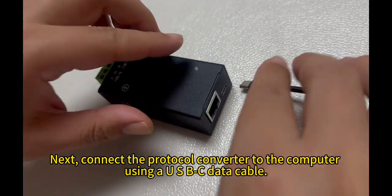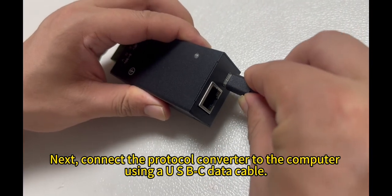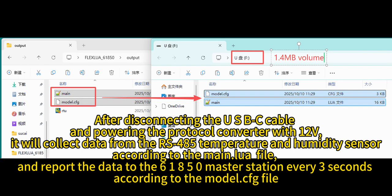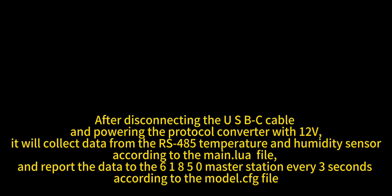Next, connect the protocol converter to the computer using a USB-C data cable. Then drag the newly generated main.lua and model.cfg files into the protocol converter's 1.4 MB USB drive to complete the entire configuration process. After disconnecting the USB-C cable and powering the protocol converter with 12 volts, it will collect data from the RS485 temperature and humidity sensor according to the main.lua file, and report the data to the 61850 master station every 3 seconds, according to the model.cfg file.